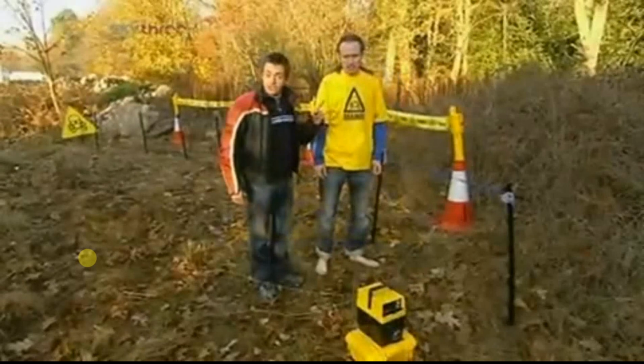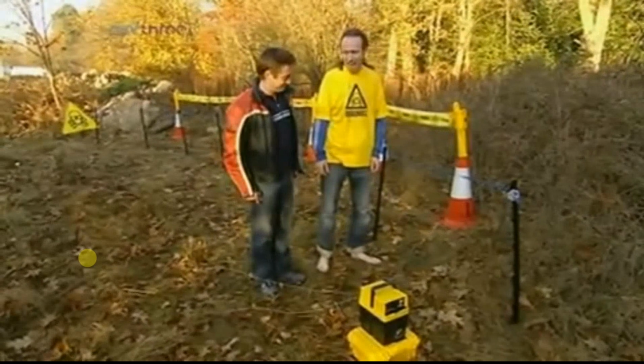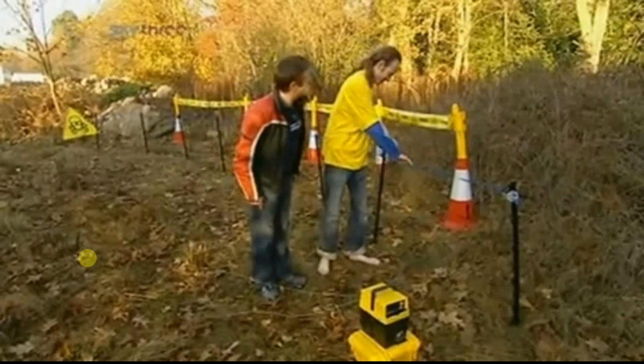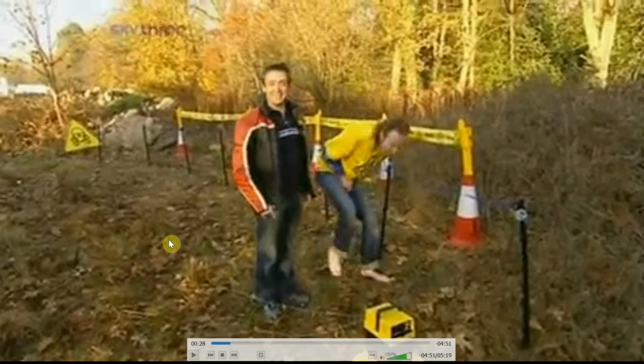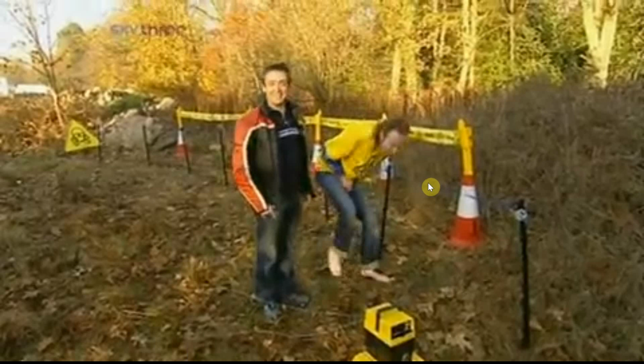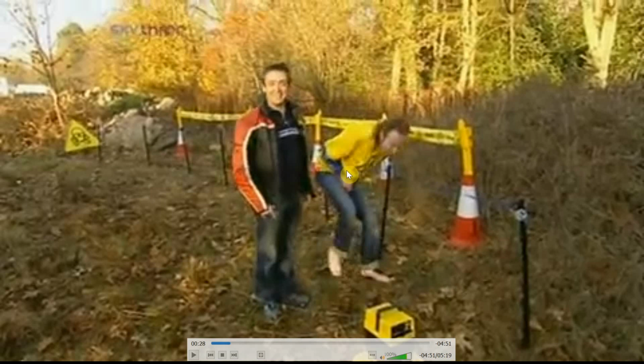This brainiac is going to touch the fence and get an electric shock. Okay, got a shock. That must mean he's completing the circuit. So the electricity was going from the wire. Where was it going into? Be obvious. Where was its next path? From the wire into him. Then where? It's got to complete a circuit. So the electricity has eventually got to make its way back to this fence. So then where? Ground through his feet. Then where?